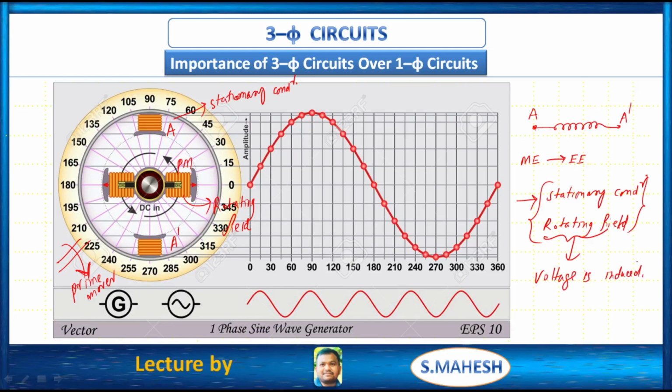By different variations of this permanent magnet, due to the prime mover force, it will rotate from 0 to 360 degrees. For example, these are the flux lines. We get the maximum flux cutting when the orientation of this permanent magnet is perpendicular to these flux lines.